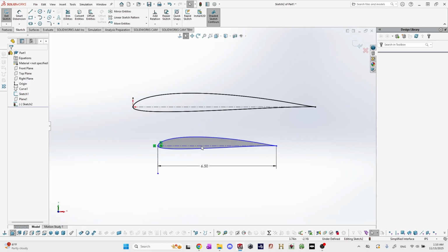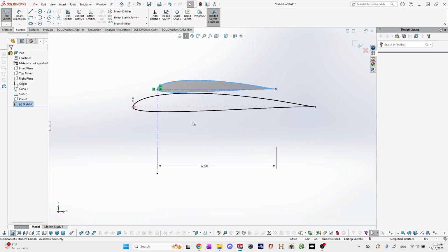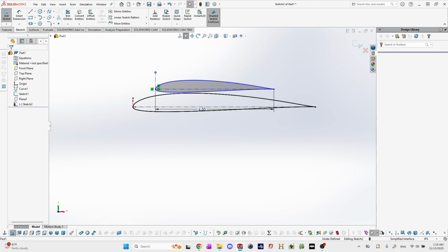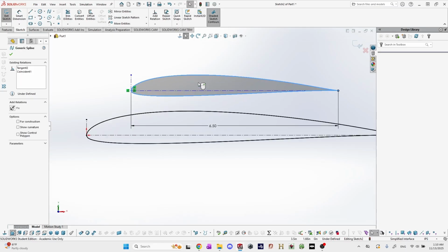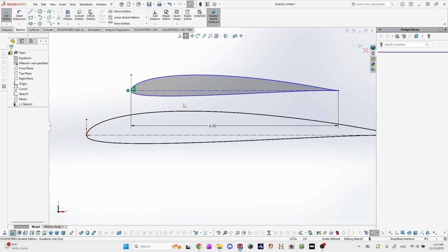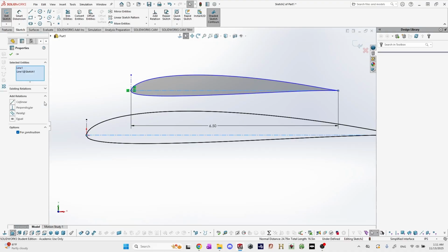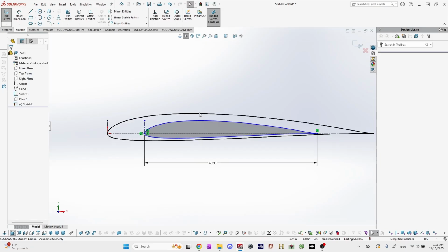And then, yeah, so if you want to add dihedral, we change a little, obviously you're going to have to add a distance, and that can just be done by a little bit of geometry. What do you want that angle to be? What's your semi-span, etc. We're assuming that we're having a straight or a flat wing, no dihedral. So what we're going to do is we're going to choose our chord line, and then we're going to choose the chord line of the root, and we're going to make them collinear.